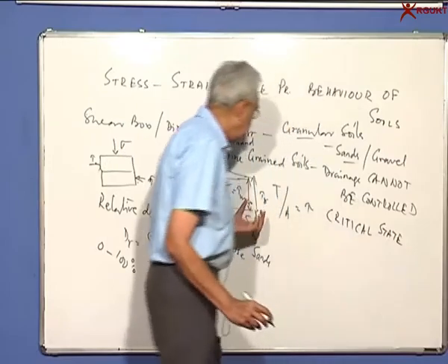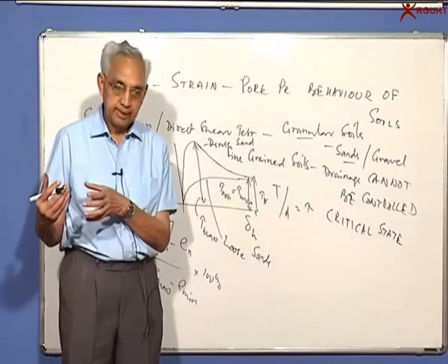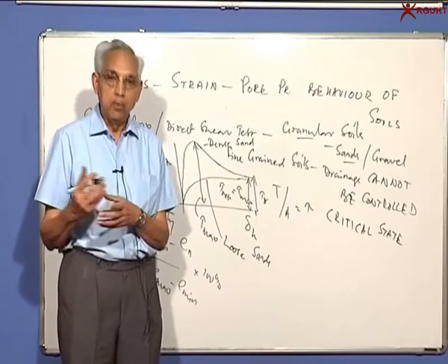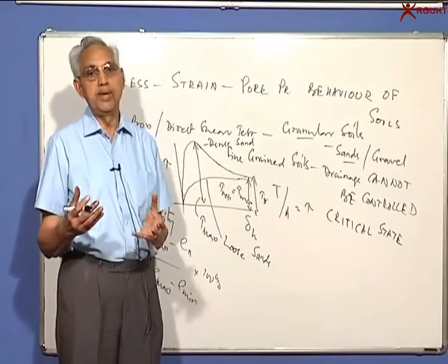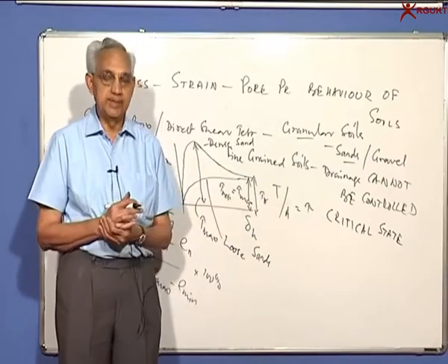And at this state, it doesn't matter what the initial condition is. The soil can start with a very low void ratio or very high void ratio. In either case, the final state is exactly the same.